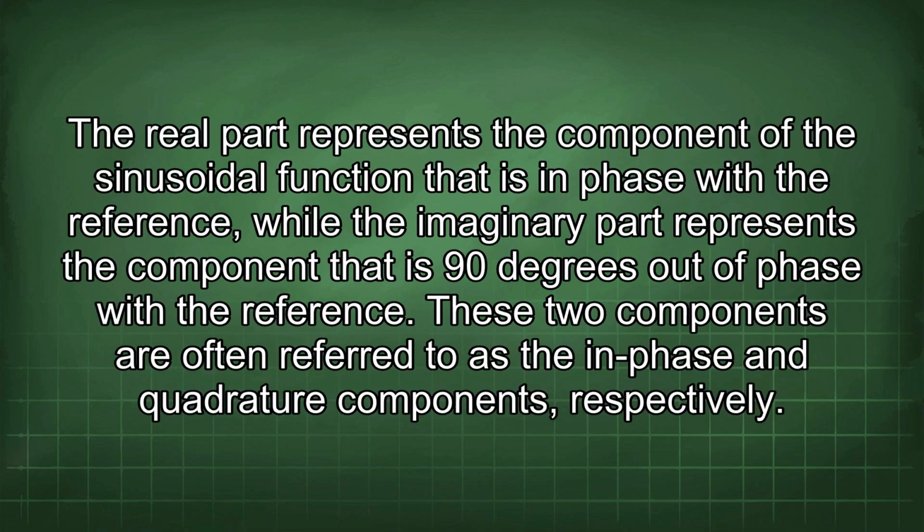The real part represents the component of the sinusoidal function that is in phase with the reference, while the imaginary part represents the component that is 90 degrees out of phase with the reference. These two components are often referred to as the in-phase and quadrature components, respectively.